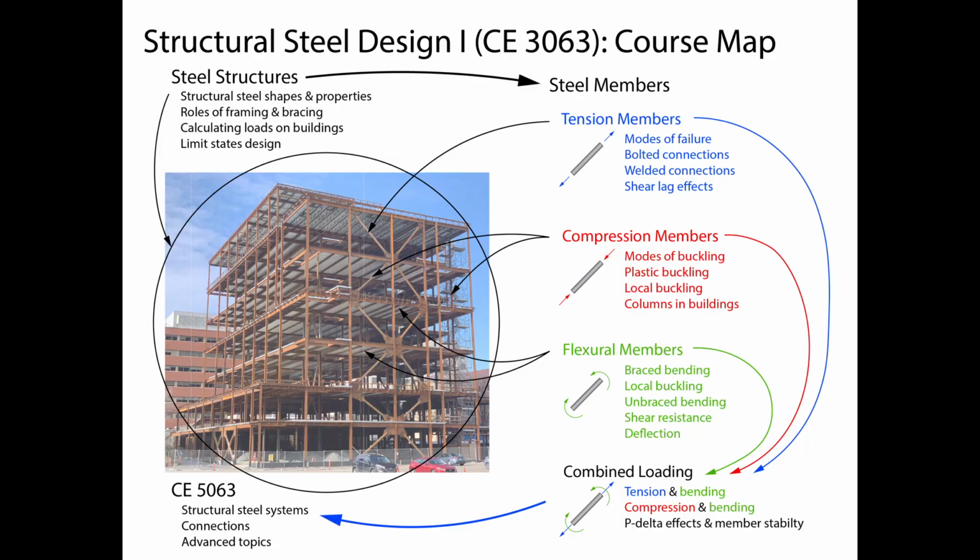Okay, so we either have just tension, just compression, or it's just working as a beam, and I guess in that case, technically, there's shear and bending that we need to consider, so we looked at the shear resistance as well as the bending resistance. Today, we're going to start looking at what happens when we have combined loading effects, and so we're going to focus first on what happens if there's a member that has bending, maybe it's from transverse loads like a uniformly distributed load or point loads, as well as tension. Okay, so some members will carry tension and bending.